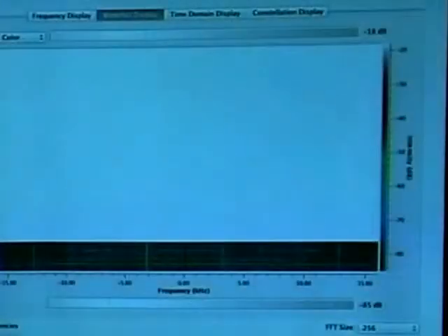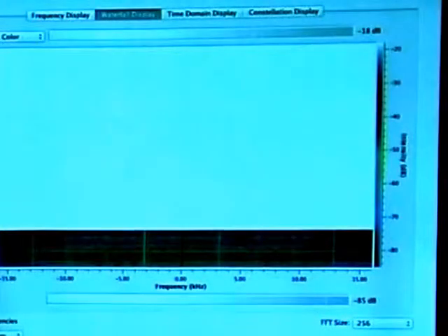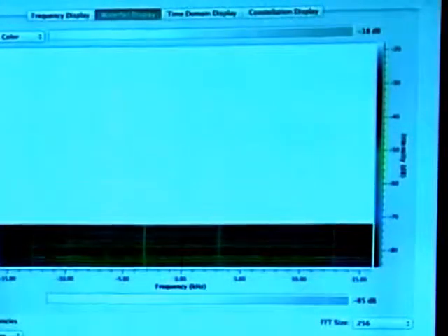So what I've done is I've tuned this radio to 2.441 gigahertz, and I'm sending out 10 megasamples or 20 megasamples per second complex to GNU Radio, and then I'm graphing the resulting spectrum. And it's scrolling up slowly. This is a waterfall diagram of the frequencies around 2.441 gigahertz, plus or minus 5 megahertz. So the red line down the middle is 2.441.